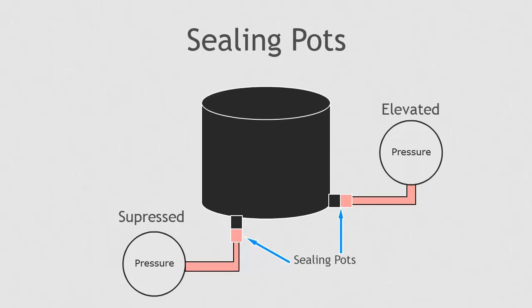A sealing pot is a device that can be filled between a transmitter and the process. It allows the pressure to be transferred to the transmitter, but is made of a material that is less affected by the process, so protects the transmitter. The capillary tube can be filled with a substance that may not be water, and so its density will need to be taken into account.